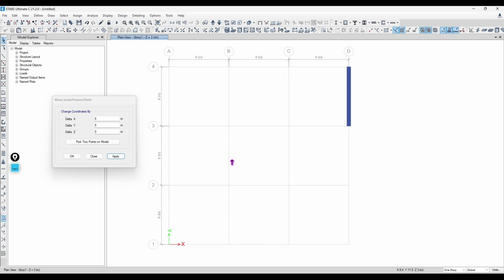Now let's say I want to move it to some kind of position that I don't know the exact dimensions of, or the exact distance. I'm just going to click, I want to move this from here to, let's say, here. I'm going to click on apply. Oh, my bad, I just select the object. And there you go, it moved it from the point you checked. Maybe you want to move it from this side to, let's say, this side. Select your beam, click on apply, and there it goes. So pretty straightforward. It's not really that hard to get your head around.